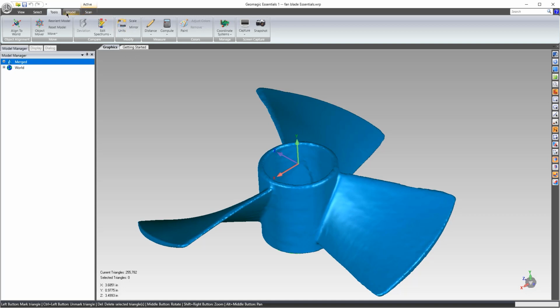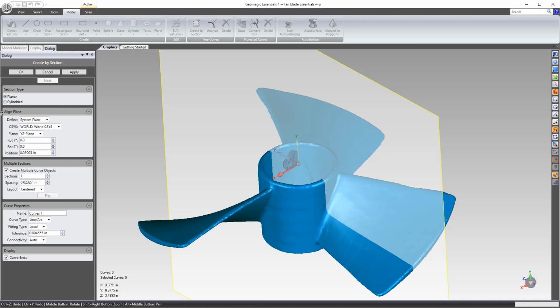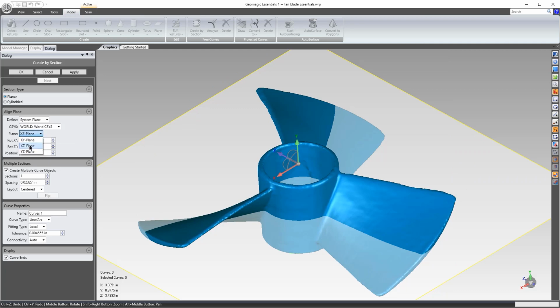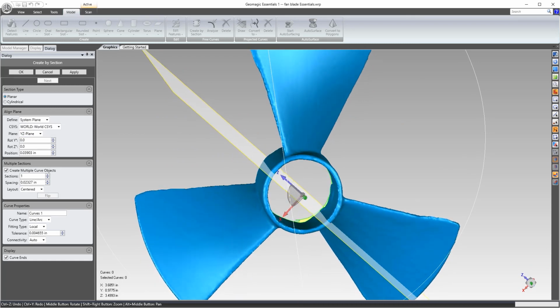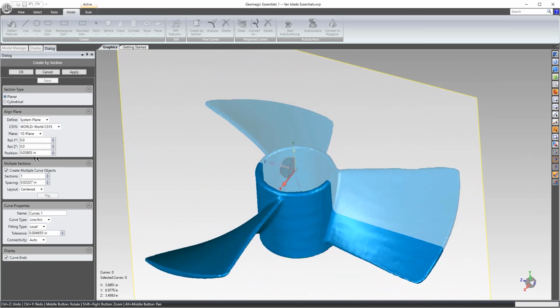So the first thing we're going to do is go ahead and cut a cross section. And you see I can actually toggle and change the cross sections over here. So I'm going to go ahead and use the YZ and slice through in that direction. And then make sure that the position is at 0, so it'll move it so it intersects the 0.